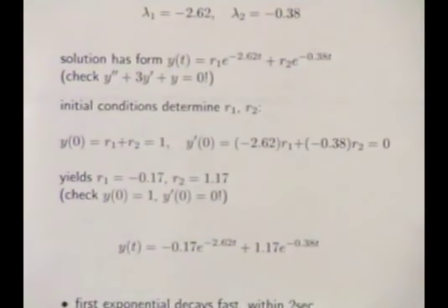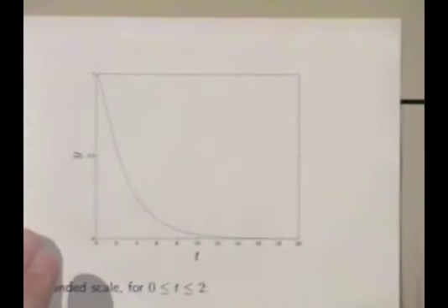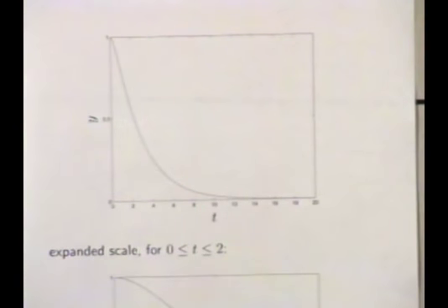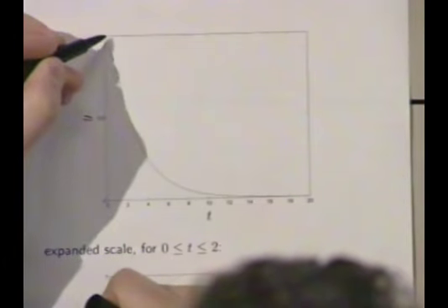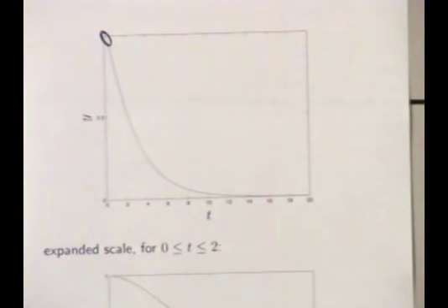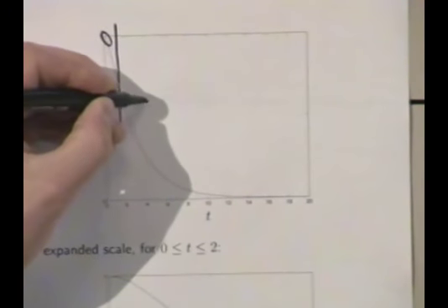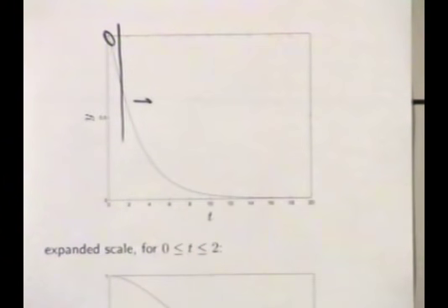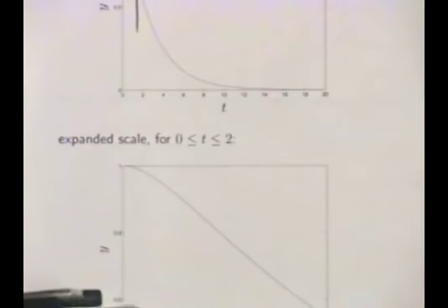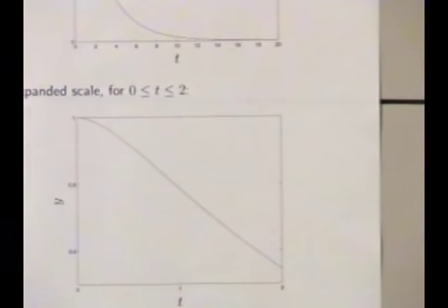Okay, so here's a picture of it. Here's a plot of it. And if you just looked at that, you'd say that's an exponential, except if your eye zoomed in right around there at the front. Sure enough, the time constants are widely enough separated that one decays rapidly and the other is slower. If I were to draw a line right here, this thing is, for all practical purposes, a single exponential with a time constant of 2.62 seconds. You're only aware of the fact that this is a second-order system for small times. And here's a plot showing what it looks like on small time.